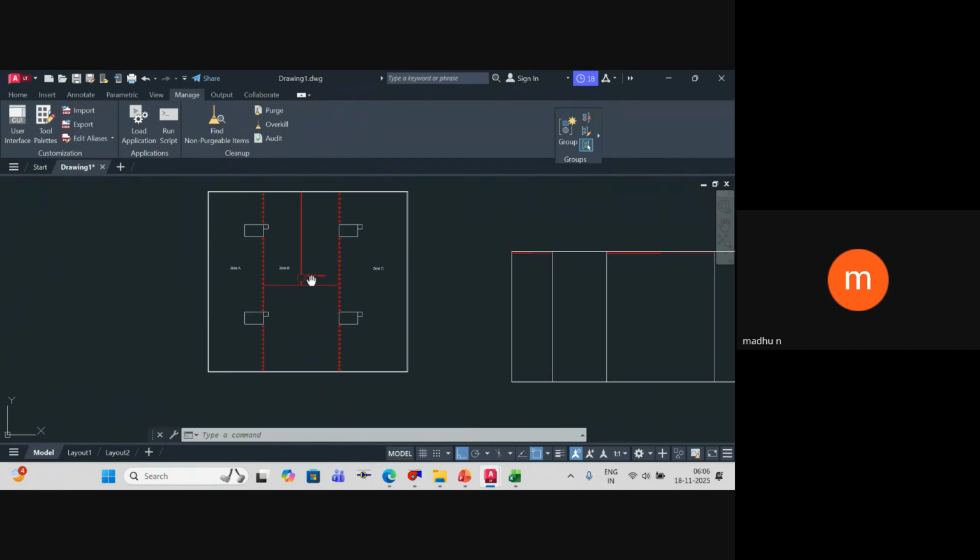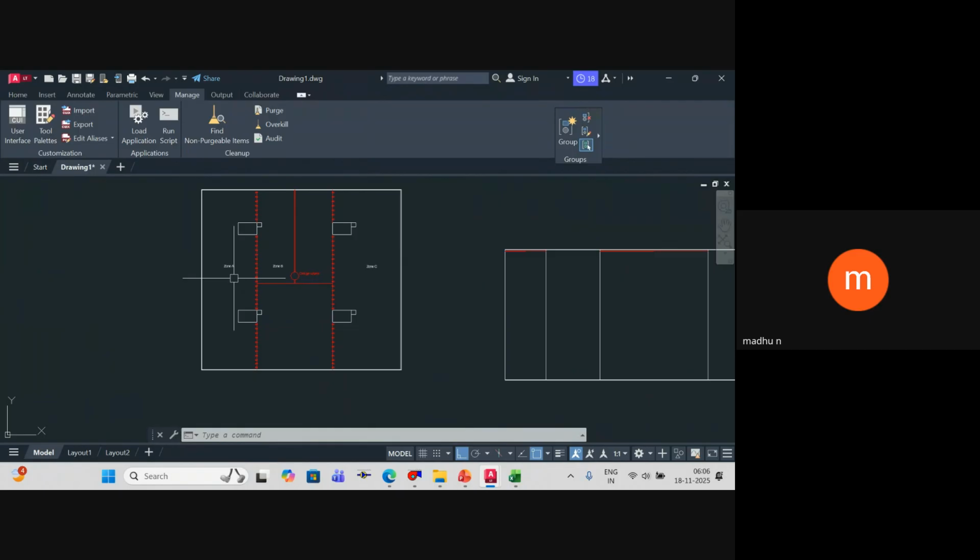if there is a fire in zone A, I think the water curtain between zone A and zone B will operate, correct? No, we don't do it like this. If you want, you can program it, but then you should have two separate deluge valves. You can't be sure at what time the fire is there, so anyway, you have to provide the total water compartment.